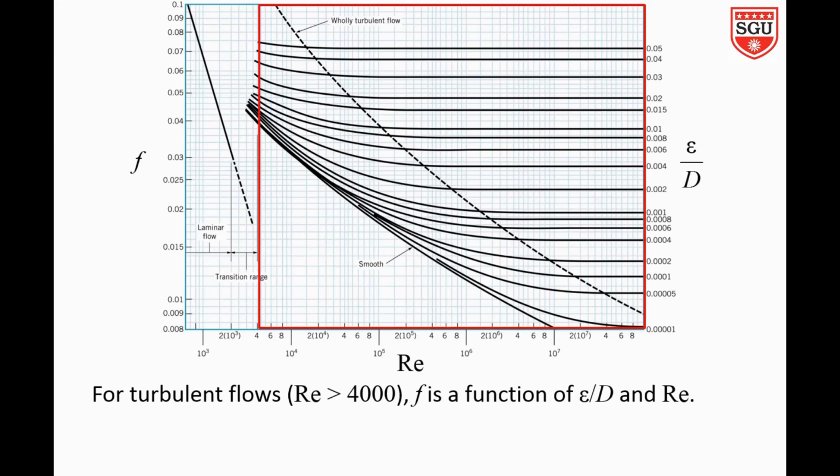For example, suppose the pipe you are examining has relative roughness of 0.002. You will use the curve shown in the orange line for determining the value of a friction factor at different Reynolds number. Now suppose Reynolds number of a flow is 10,000. Draw a vertical line from 10,000 on the x-axis until it reaches the orange line. Now draw the horizontal line from the intersecting point to the y-axis and read the friction factor. For this example, the friction factor is approximately 0.03.